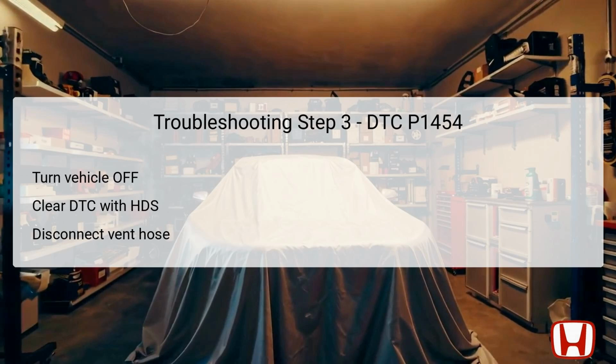With the vehicle again switched to on mode, the technician needs to check the parameters of the FTP sensor using the HDS, as previously. This repeated measurement of pressure readings against thresholds will help verify if the vent hose is obstructed or if the FTP sensor itself is malfunctioning. If abnormalities are discovered, it indicates a blockage either in the vent hose or the EVAP system that requires resolution.